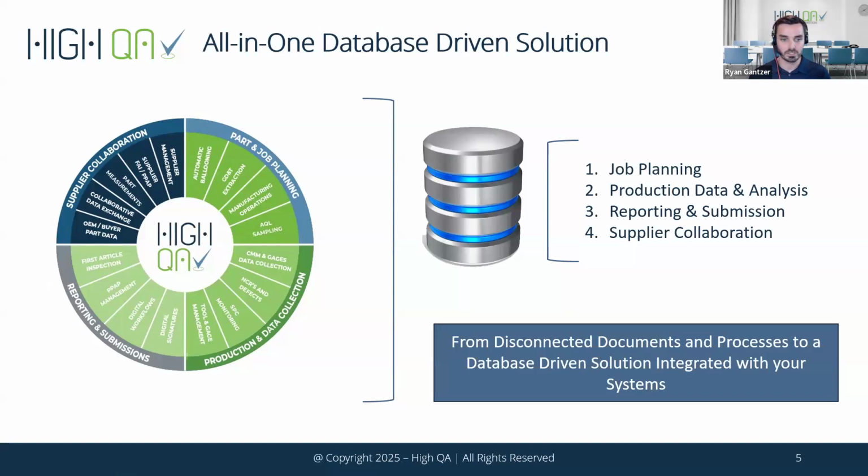So methods for data collection, we have various methods. At the end of the day, we just want to get the results into the database. So we can connect automatically to CMMs, VMMs, Faro arms, if it runs on software. Like I said, automatically as a background running operation, bringing in those results. We also have a digital shop floor data collection module for your manual checks. Think calipers, mics, stuff like that. We're digitally out on the shop floor. You can enter in your results as you're making the measurements, and that'll flow automatically into the database.